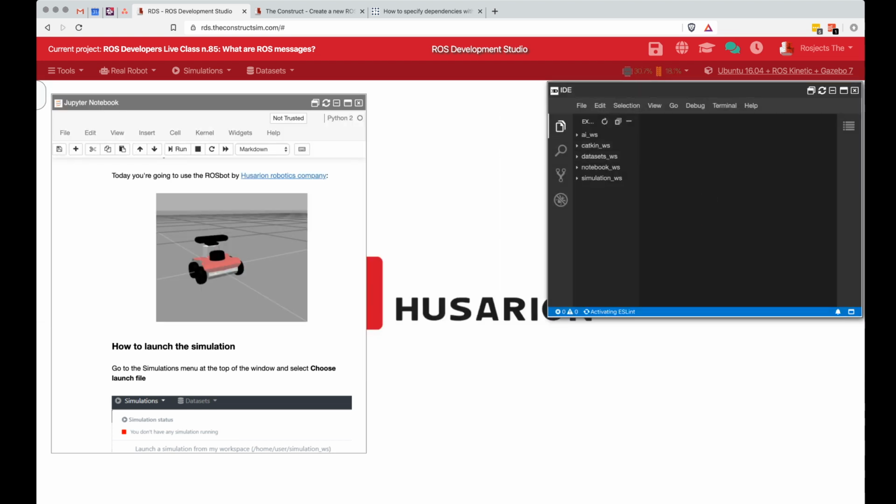And here you can see all my files. There are different workspaces on this file explorer, and one is called the simulation workspace. If you click in there, you will see it's a ROS workspace called simulation workspace. Then inside src, you can see the ROSbot robot. Here are all the packages related to the simulation. So that's already included inside this ROSject.